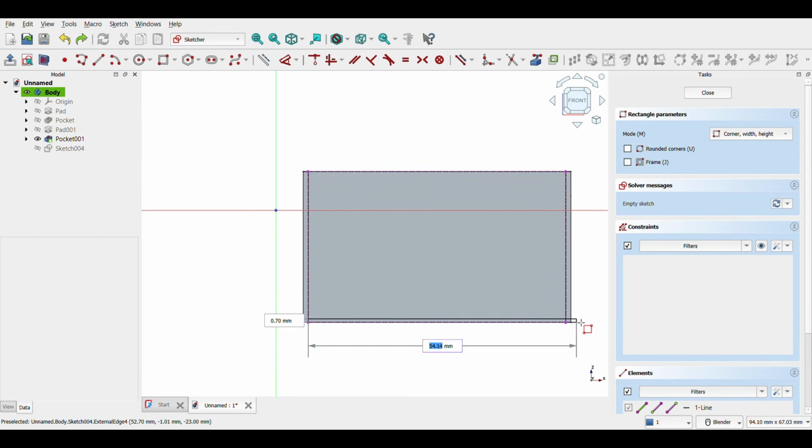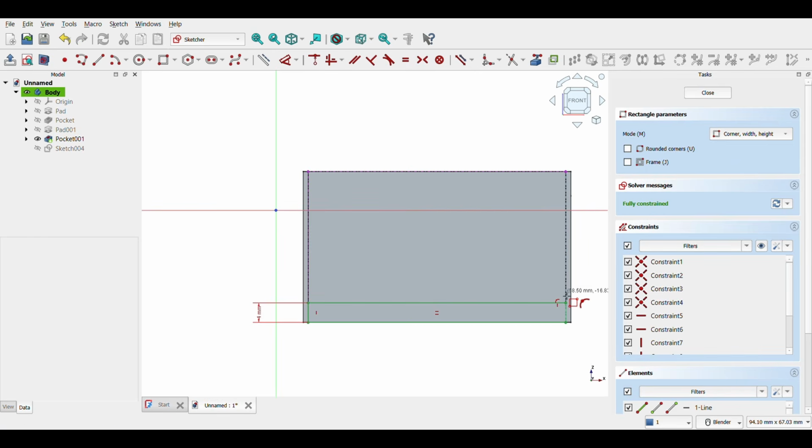One will be the base for the second. The first rectangle is 4 mm per 52 mm. Then the second rectangle will be 6 mm per 52 mm. This is not the correct method, but is good for now. We will cancel the first rectangle, close the sketch.